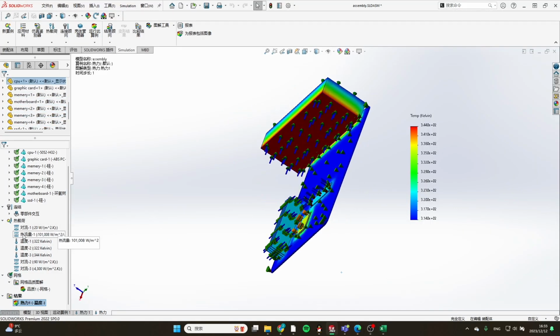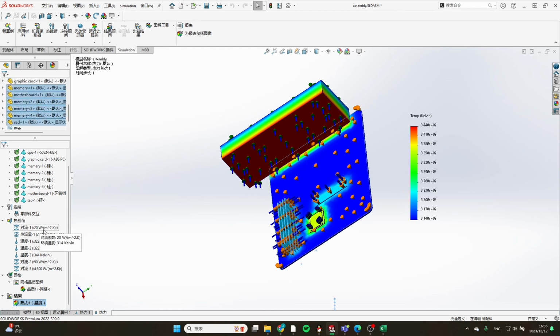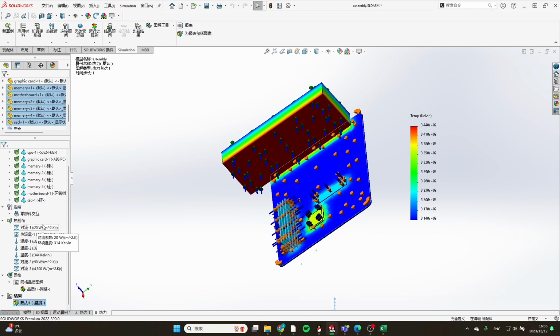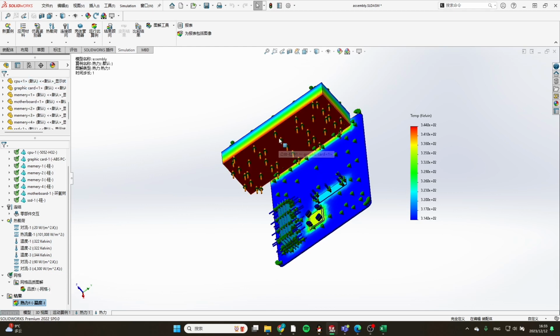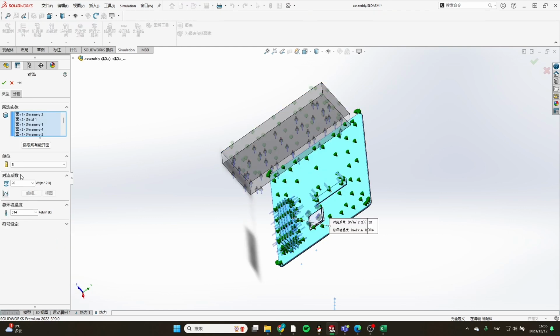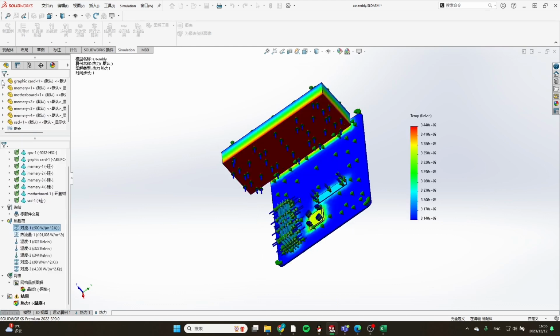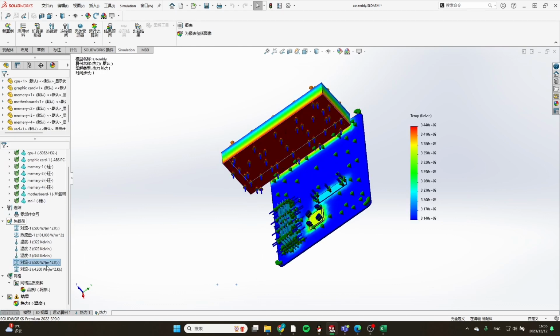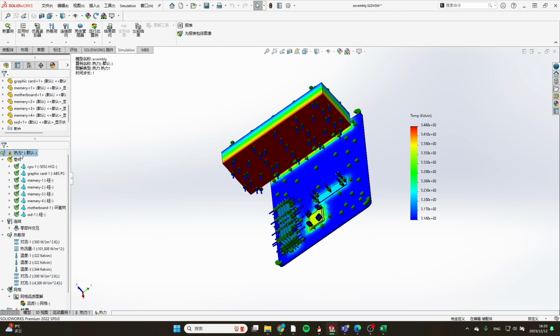So right here, this value already has a set of outcomes from common settings: 20 watts per meter square Kelvin for the motherboard, 90 for a stronger one, so it's 90 for the GPU. I'm going to change it to an extremely high value, like 500 for both, and hold the value for the CPU constant and see the result.